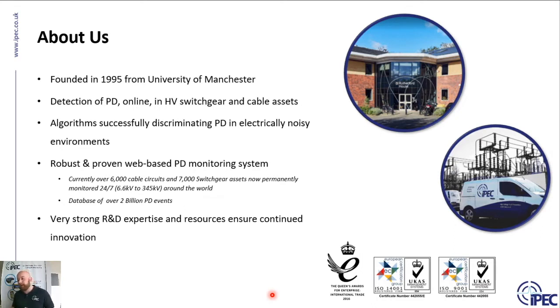IPEC is very specifically well known for our ability to differentiate PD from background noise. With online partial discharge there is a susceptibility to noise interference, and that's one of the biggest known issues in the industry. Throughout our product range, in our more advanced permanent monitoring systems or simpler handheld instrumentation, we make sure there's a function to differentiate PD from noise. I'll come into some details about that as we go through the presentation, but that's what we're quite well known for.